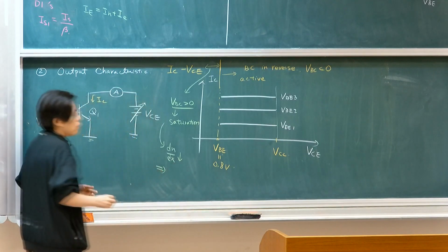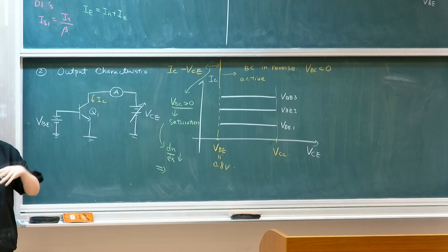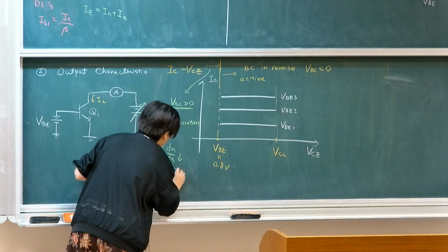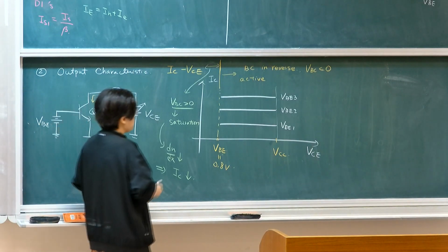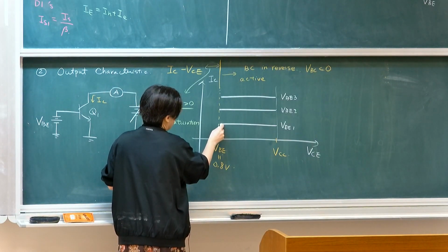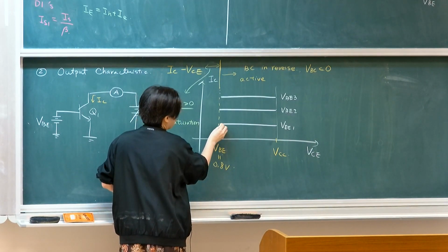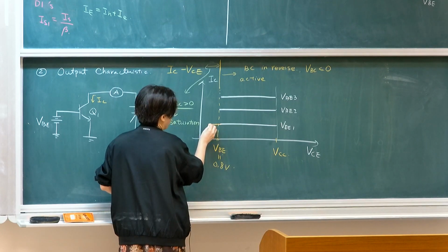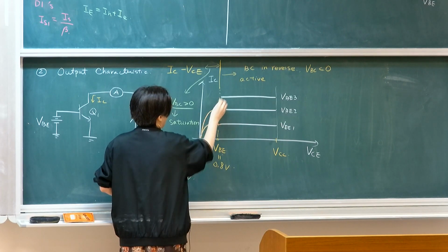Therefore, you no longer have a zero at the back. There's no longer suction. You're forward biasing as well. So both sides are creating large minority carrier concentration inside the base and then reducing the gradient. Therefore, you expect IC to decrease, of course. So then what happens is that you assume that it will decay. But in most cases, in saturation, you're assuming that it will decay well, but it will take a while. And we're going to explain that in a little bit.